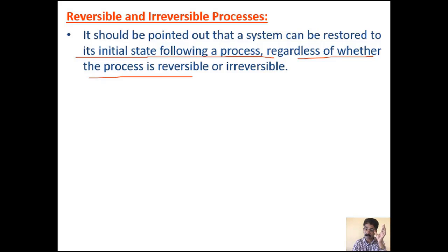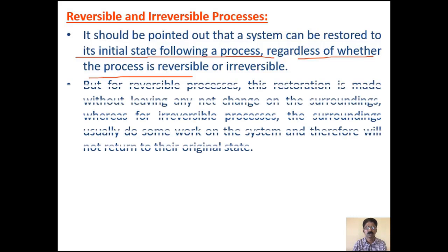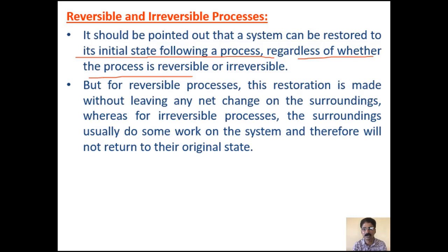Even for an irreversible process you can bring the system to its initial state, no issue. Just now I told you, you can bring it. But during the process what is happening? You are doing additional work on the system and you are removing additional heat from the system. So for the surroundings, there is some trace left out. So the surroundings don't come to their initial state.